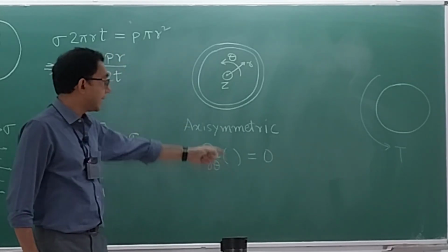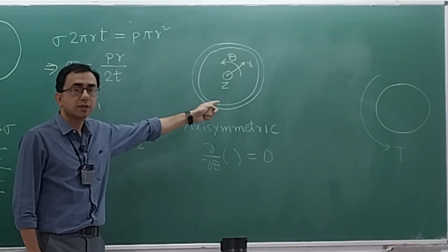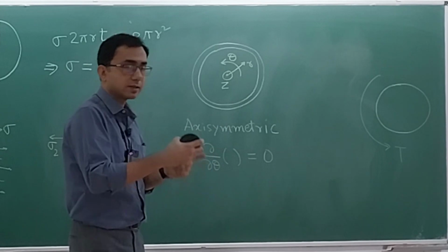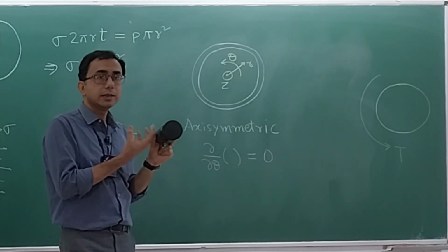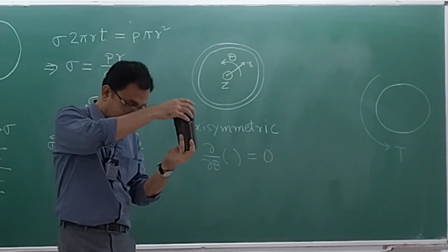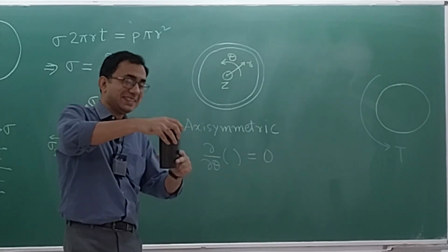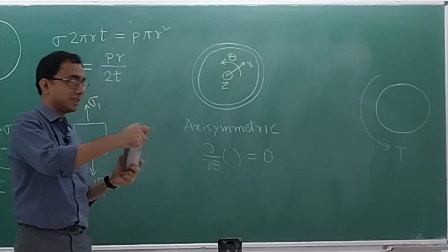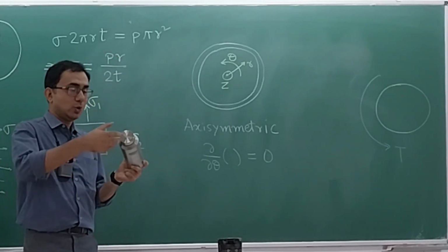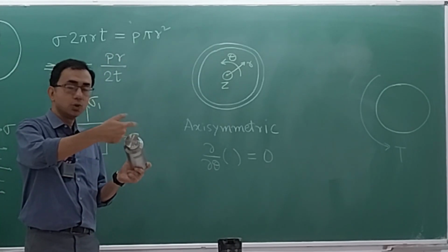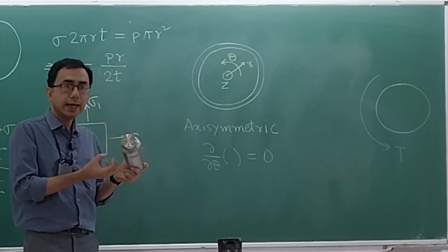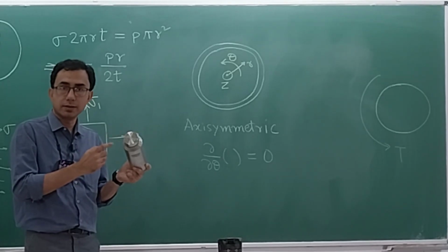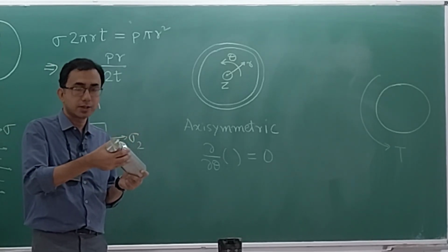Now, do we have that kind of twisting action in this thin walled pressure vessel? You have the thin walled pressure vessel like this. The fluid is exerting pressure in which direction? You do not have any twisting action. You only have the load acting radially from the inside, so that pressure is acting in the radial direction.